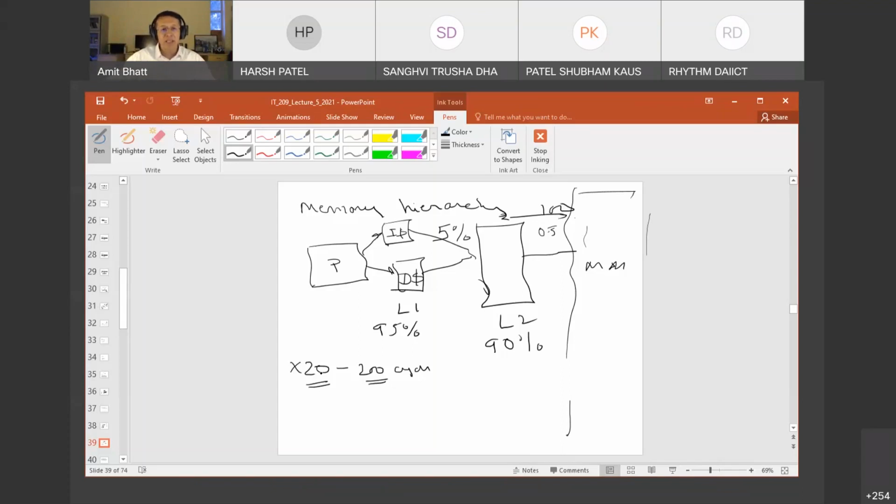So the manufacturers would say that you give me a surety that you will be able to do this in 100 cycles all the time, right? I want a hard deadline that it should be done in 100 cycles. I don't want it to go to 200 cycles, or in worst case 2000 cycles. I also don't care if you can finish it in 20 cycles. I don't want that fast an operation, but I want a guarantee from you that it should be done in 100 cycles. And this is known as a hard real-time system, which says 100 cycles, and it is an absolute hard deadline.